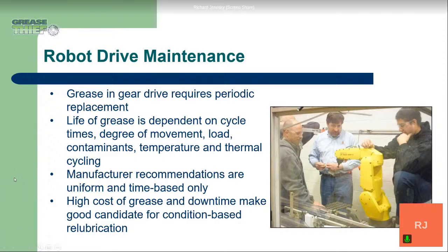When we think about it in different facilities, each robot will have a different task. So it's going to be important to optimize the maintenance and lubrication frequency for each robot based on the things that we just mentioned, because if they're all doing different jobs, they're not going to need the same maintenance schedule, and we'll be able to set them up appropriately to make sure that we're optimizing our robots' use.